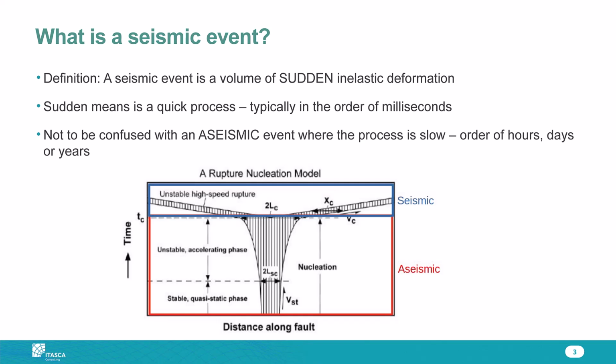It reaches a point where it releases a lot of energy very quickly, and only this part is considered to be seismic. That is typically the earthquake, the waves that we feel when that rupture occurs, and we hear about it on the news, and they explain it to us in terms of Richter magnitude. That is the seismic part. But the majority of the deformation initially, that took a very long time to occur, was aseismic.